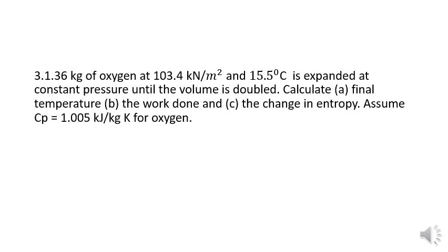1.36 kg of oxygen at 103.4 kilonewton per meter square and 15.5 degrees centigrade is expanded at constant pressure until its volume is doubled. Calculate the final temperature, work done, and change in entropy. Assume the Cp value for oxygen.